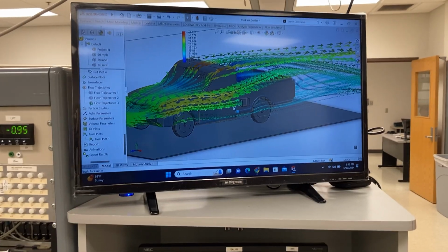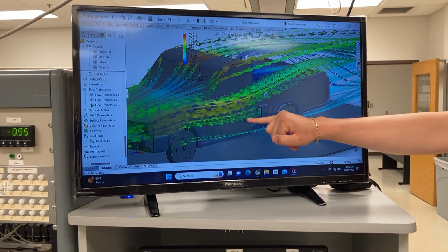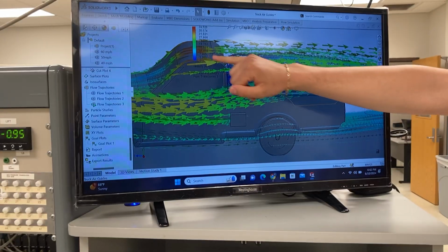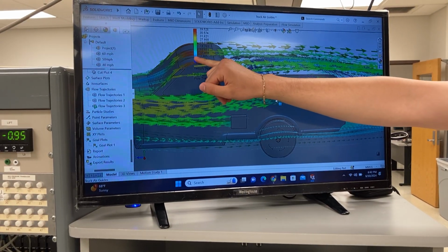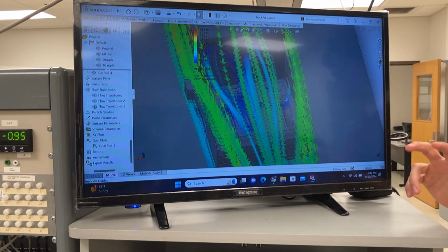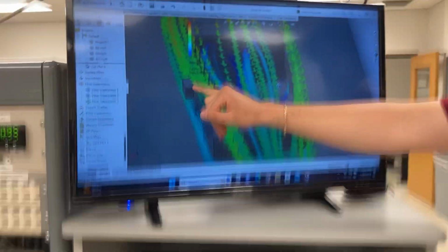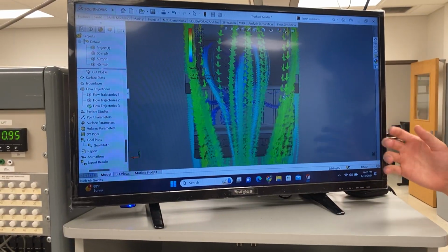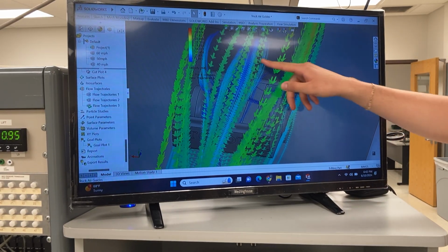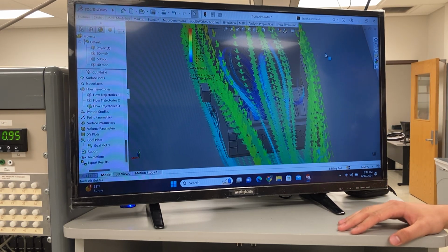Oh, yeah. Okay. We can see how a lot of air is channeled into the bed through the scoops. We can see, as we saw in our velocity plots, how the wind speeds up a lot by the roof of the truck. And we can see the low pressure or air bubble zone created in the bed of all of the models, but the air scoops really make it bigger. We can see the vortices created in the X and Y dimensions. Do you want to add anything?